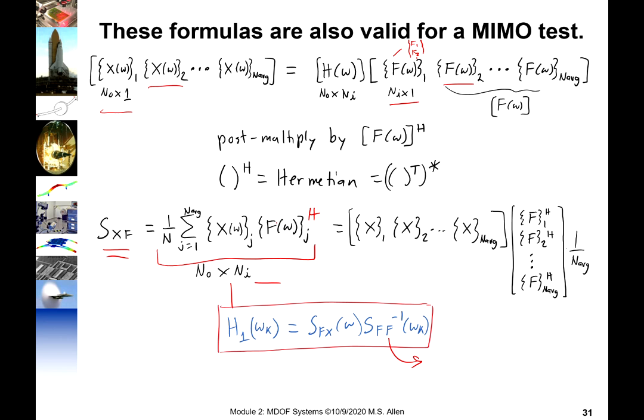Today, more and more, it's possible to record time histories, and in most important tests, the time histories will actually be streamed and recorded. And you can get gigs and gigs of data, but the test is so expensive it's worth saving all that data. A lot of the analyzers, though, still use this approach and will only store the autospectrum and cross-spectrum. They won't store all the individual time histories.